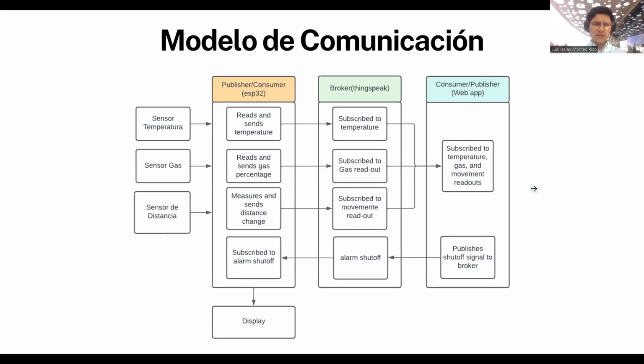They send readings of analog signals, converted into electricity, to the ESP32, where it processes these signals, sends them as numbers through MQTT to the broker, and then the broker registers them and sends the readings over to our web application, which will eventually show them to our user.